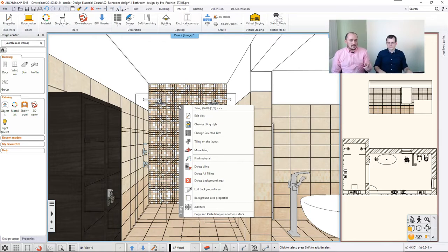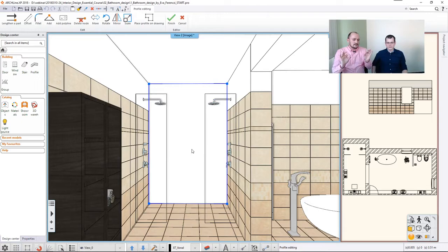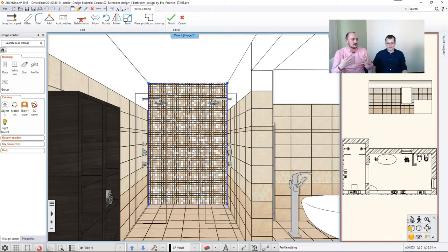And the same way I used the 2D layout just 5 minutes before, I can do the same thing here in the 3D layout. If I say I edit the background area here, then the software drafts the background area contour here. If the tiles disappear, don't worry, they did not really disappear. Sometimes the software is getting rid of them, because at that point maybe they are not that necessary. And sometimes when the performance drops, the software measures how it performs on that computer, and if the performance drops, it is simply skipping the tiles for a temporary time.